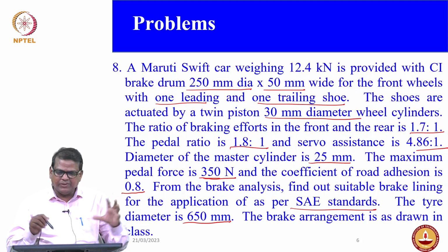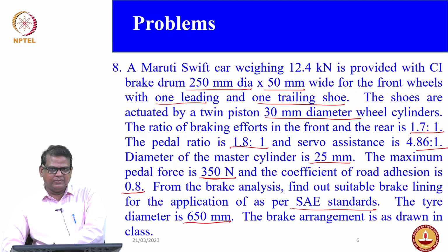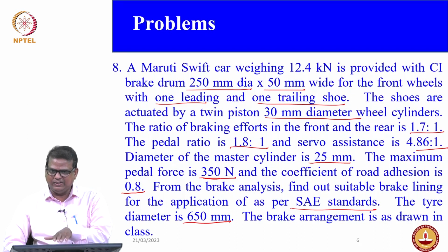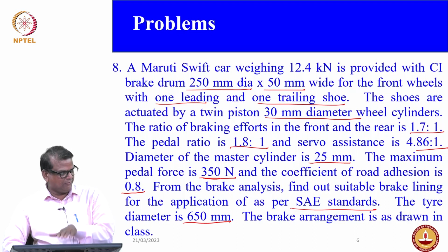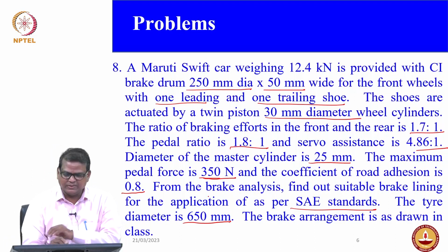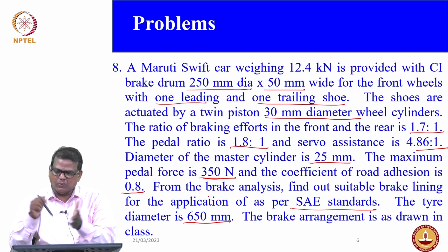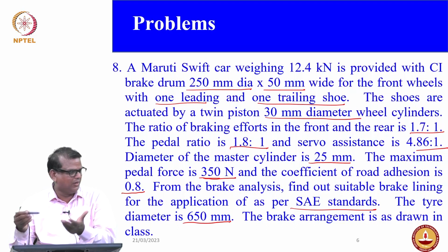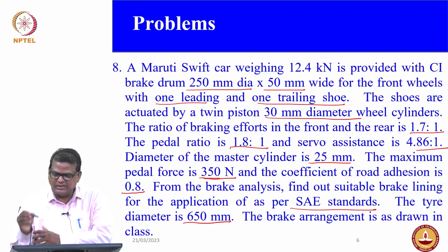I will give other information also, and look at how you apply a brake. You have to use your pedal force, which is 350 Newton, clearly given. From there you have a lever mechanism. The lever mechanism will enhance the force 1.8 times, right? From there you have a vacuum booster that will further enhance your braking effort 4.86 times, that is clearly given.